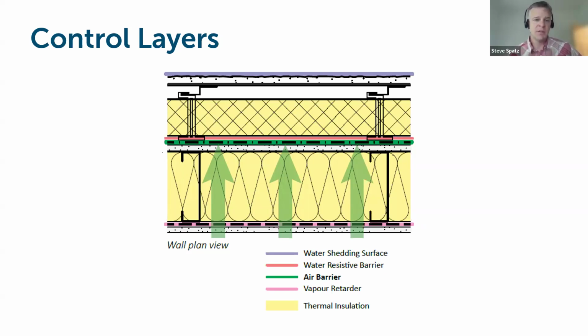So the pink line being the weather resistant barrier over the sheathing here defined as the air barrier as well, cavity insulation, and then the final pink layer on the inside of the vapor control, vapor retarder. And those arrows are giving the indication of where the vapor flow will be into that assembly, and the heat transfer flow will be during the heating season.